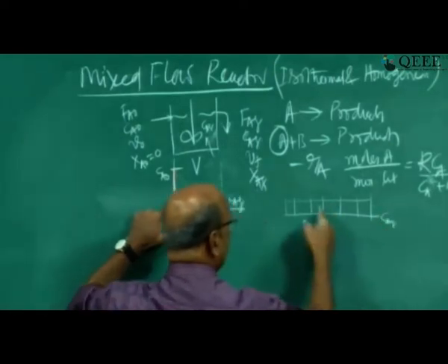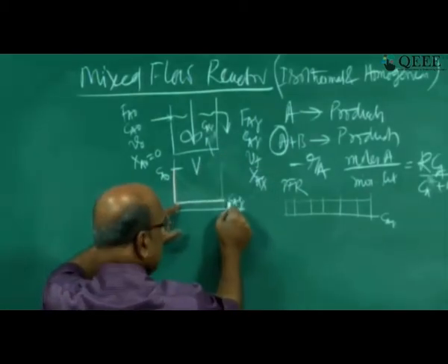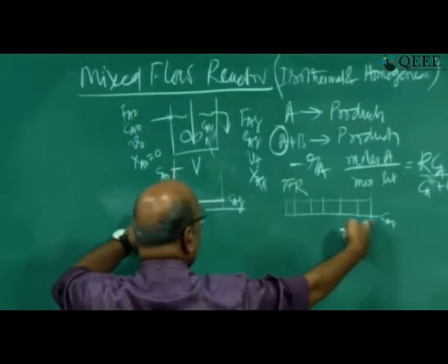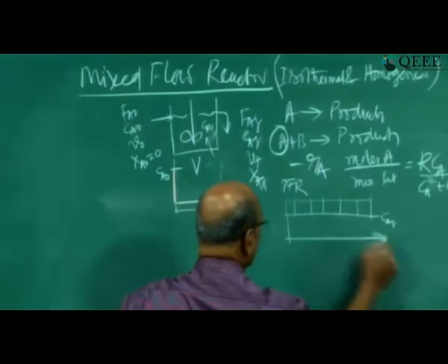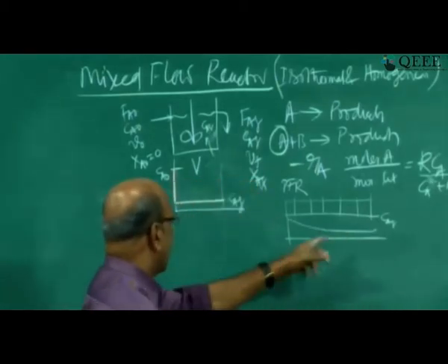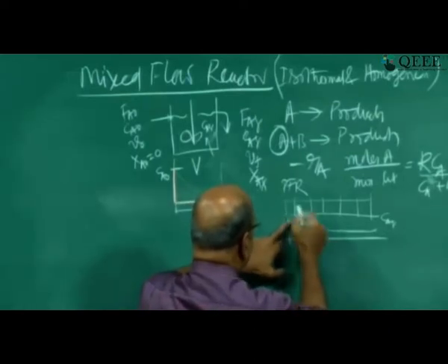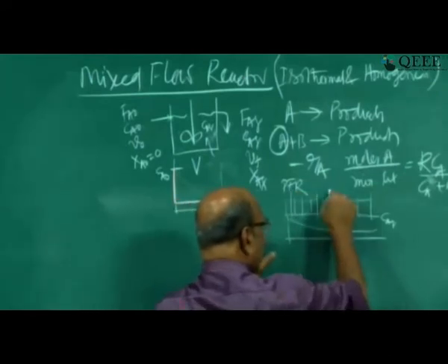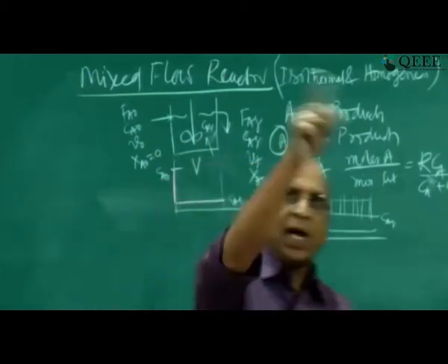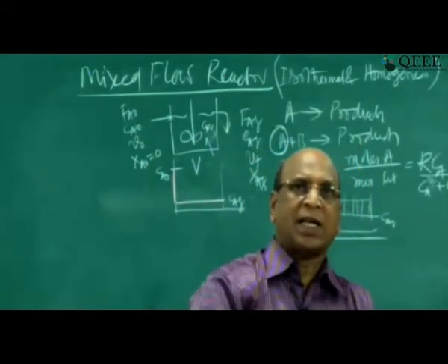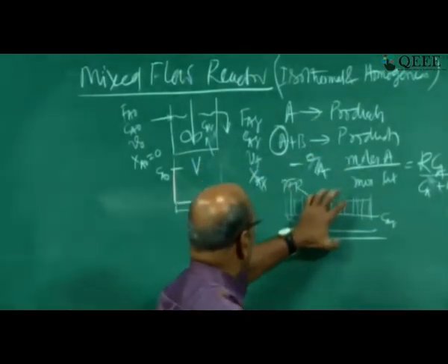Here also CIF, this is a plug flow, PFR. Here also I have mixed flow, this is also CIF. So these two concentrations are the same, but how it is reached in plug flow is totally different. This is the one along the length. That is why here when I have the CA0, it becomes slightly less than CA0, and then I have a rate. So if I calculate the number of rates inside a PFR, we have an infinite number of rates. In fact, the meaning of the integral 0 to XA dXA by minus rA is a kind of average. So that is why plug flow reactor is much better,